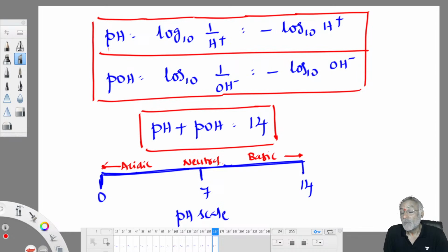Moreover, over and above, extreme pH water damages the property. Extreme pH means close to 0, close to 14, which damages the property. Therefore, we try to maintain neutral pH, close to neutral. That is always better to protect property. From a drinking point of view, it is absolutely safe. There is no problem at all with respect to pH. But from a property point of view, it is objectionable. That's why pH needs to be measured.